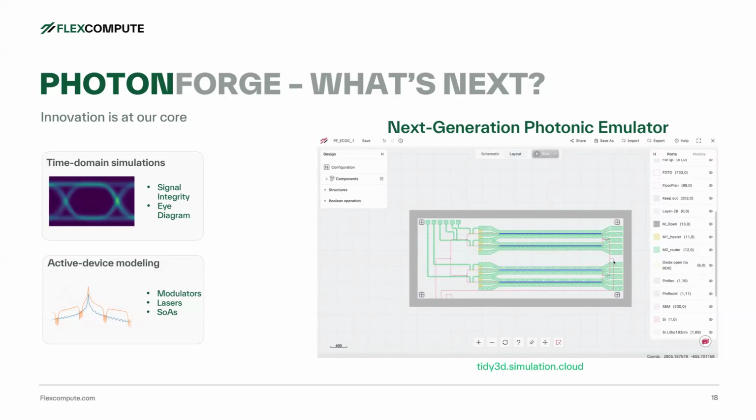Actually, I do have one more question. How would you incorporate photonic wire bonds in this framework? Well, photonic wire bonds, you just run an FDTD simulation, right? You take whatever your fiber is. The tricky thing with the photonic wire bond is that it's a 3D curved geometry, so you want to make sure you mesh very well. Usually these FDTD simulations, because of the rectangular grid, work really well for planar circuits. But once you start doing things like photonic wire bonds, where you have curved things and narrow tapers at the end of the waveguide where you're connecting it, you just need to mesh it a lot. Then you have an input port, which is your fiber, and the output port, which is your waveguide, and you just build an S parameter for that. And that's your model. Yeah, that's fair.